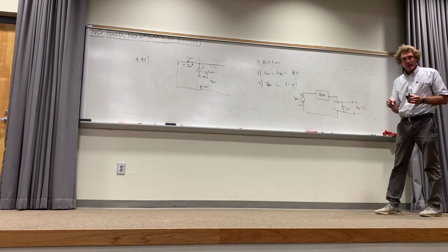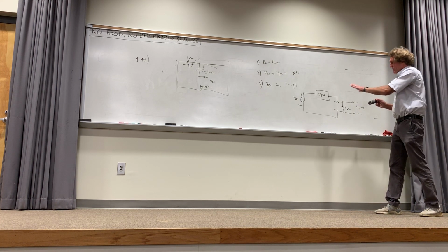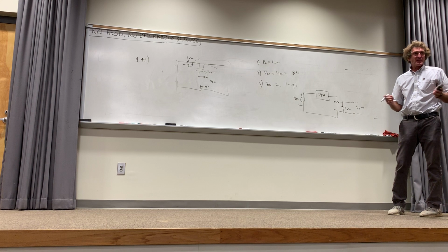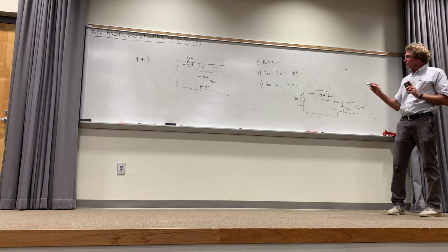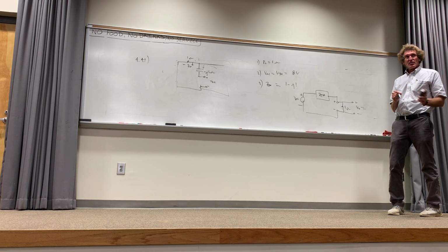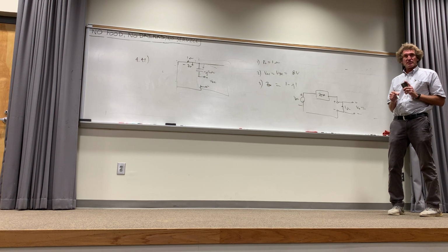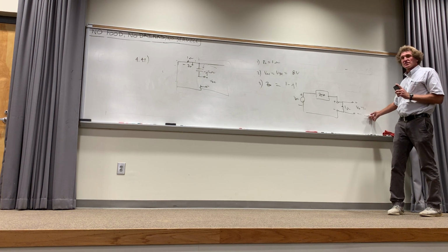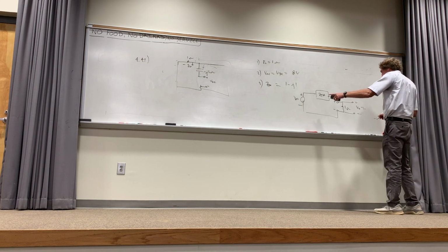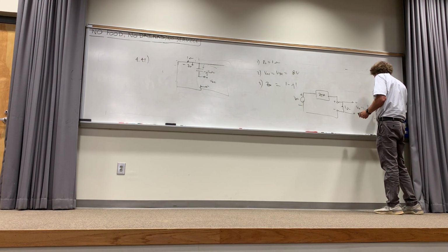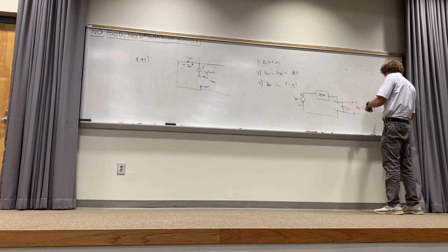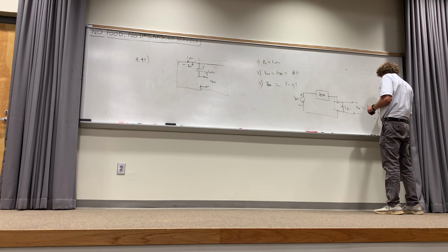Do you all agree? Now, I didn't even put in the values yet, but I'm going to show you something, and this should be obvious. Do you all see here, once you have open circuit voltage, the only thing left to do is voltage division? The only thing I need to do is divide the voltage to get this, don't I, class? I can say that V out is really VOC, and then it's going to be times this, in this case 1 ohm, or whatever the load is, over Z Thevenin, right, plus 1.